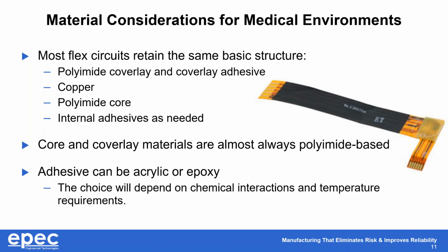Just as I said, almost all core and coverlay materials are polyimide based. That's just the nature of the flex industry. Adhesives can vary a little bit more. You can end up with acrylic or epoxy, and even more extreme polyimide based adhesives.